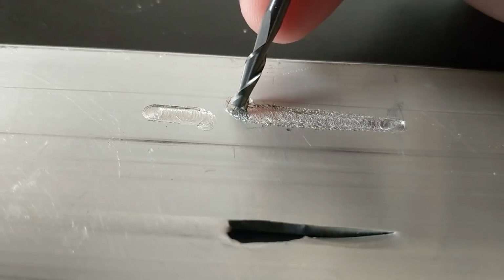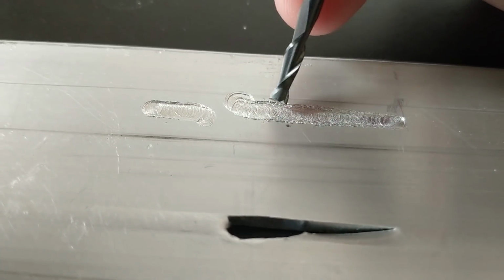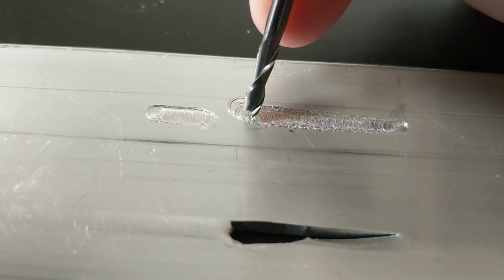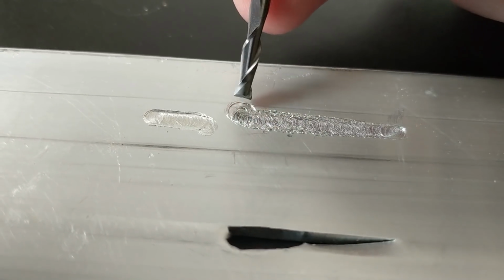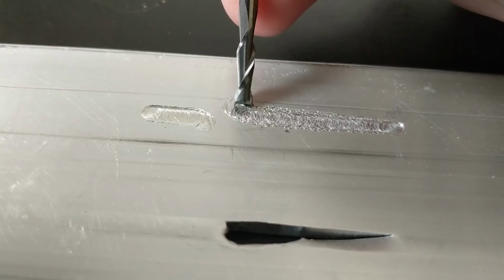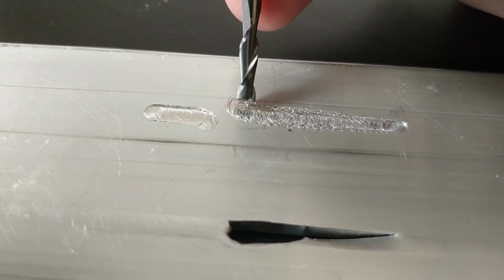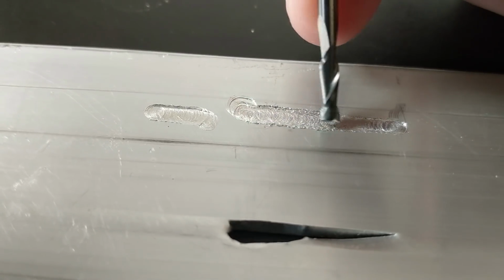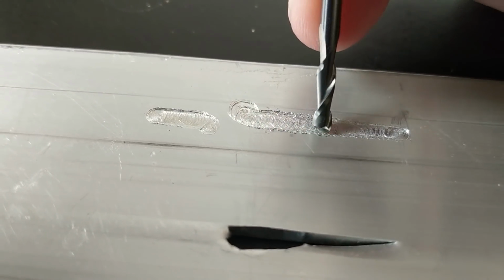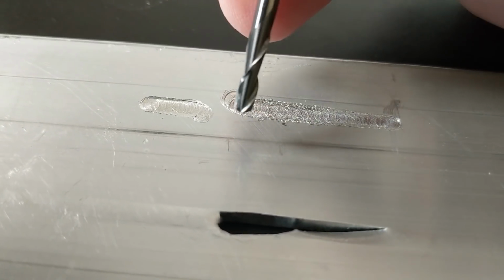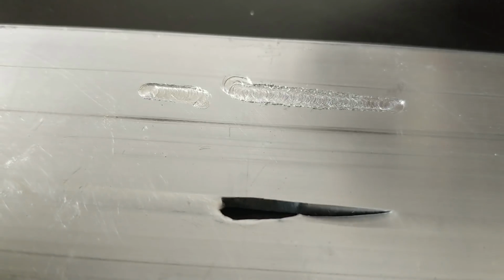Now this was a previous cut that I did with twice the feed rate and twice the depth of cut. And look at the size of that circle. Keep in mind that that circle was made with this bit. So look at how much flex that bit is having before it finds its home and starts to carve down the wall. And even then, it's bouncing back and forth across that channel. So just so much movement from this bit and this machine.